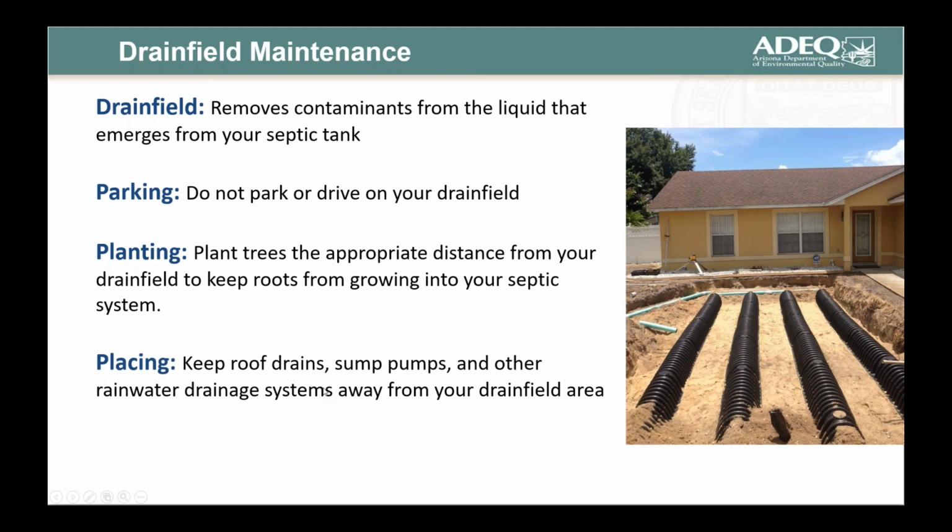Placing. Keep roof drains, sump pumps, and other rainwater drainage products away from your drain field area. This reminds me of a property that I inspected in the Nogales area. Picture this: the backyard, and all the roof water runoff went straight off and flowed right into their disposal field. And I got out on the side and said, sorry folks, this ain't gonna work. Put yourself a roof gutter over here and then drain your stormwater off over here, not onto your disposal field.